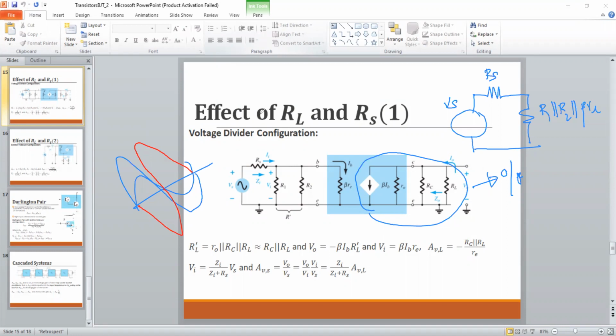This is actually what I want to highlight during this session. If I give a transistor circuit, ideally you can do the DC analysis and the biasing, and select the currents, voltages and resistors accordingly based on the given values. Either you may be given the currents and voltages and asked to evaluate the resistances, or you may be given the resistance values and asked to evaluate the operating point parameters. Then if you are given an external AC input, you can analyze the circuit in the AC domain. The same circuit can be simplified to an AC equivalent model by replacing capacitors with short circuits and inductors with open circuits, and the effect of the source can be ignored by setting the source voltage to zero.